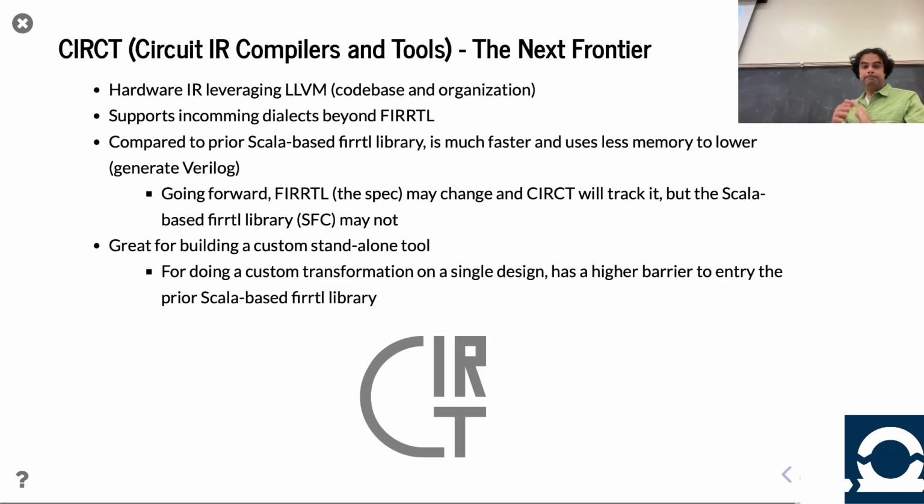Although Chisel still uses the front end to feed into CIRCT, that's kind of standard. And this Scala FIRRTL library we're using has been end of life. So in the future, if they were to change FIRRTL, which they haven't done too often, that will be reflected both in the Chisel front end and in this tool called firtool in CIRCT. It may not necessarily be reflected inside that Scala-based FIRRTL library, right? Shucks. But that gap for now isn't too bad, but maybe in a couple of years there'll be a bigger gap. But CIRCT's really cool.